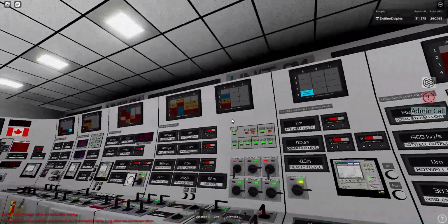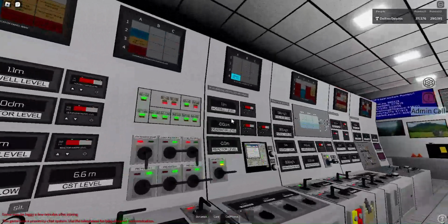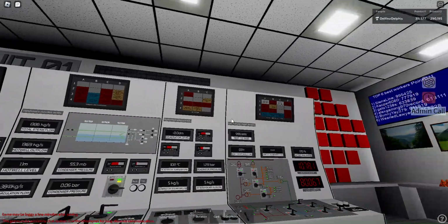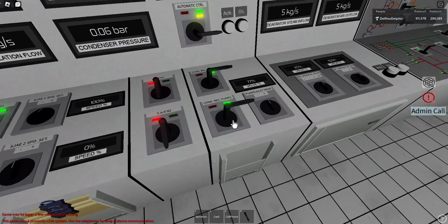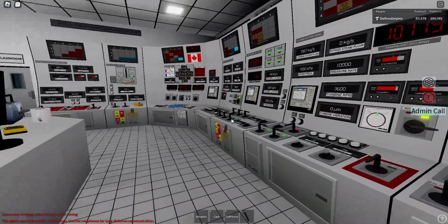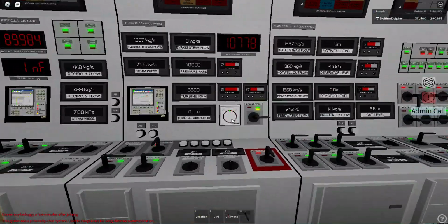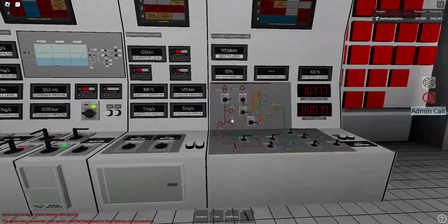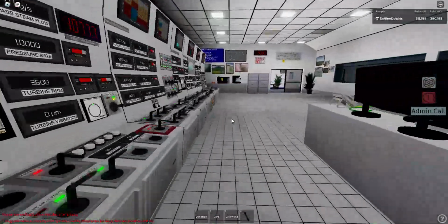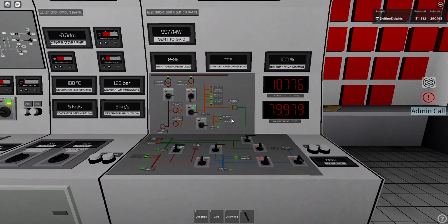Let's have a look at the annunciators. Nothing, this is only automatic control. I think we are missing the automatic control annunciator for the condensate. I will have to probably put it. Yeah, and this is how it works. That's basically all of everything. So you can see the auto control is really managing this a lot. The only thing that I really need to do is to change the power and then to set up the Deaerator correctly to have it all working.